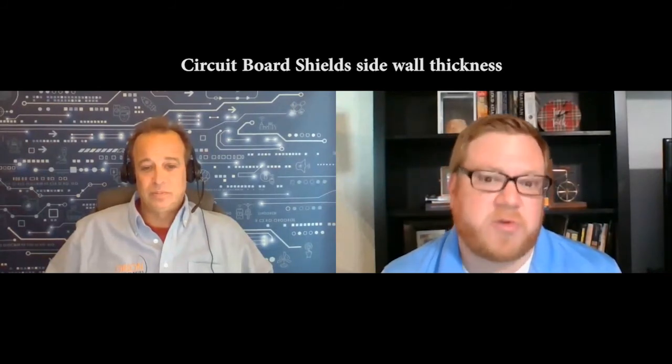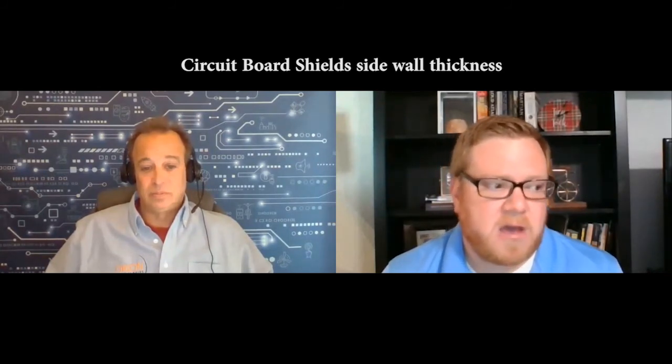Yeah, that's kind of what we were talking about too. One thing to take into account is how large you can make your trace pattern. So if you only have 35 thousandths of an inch of room, then you need to use a little bit thinner metal to keep the 3.5 material thickness minimum that we recommend. There also comes into terms how small the shield is.